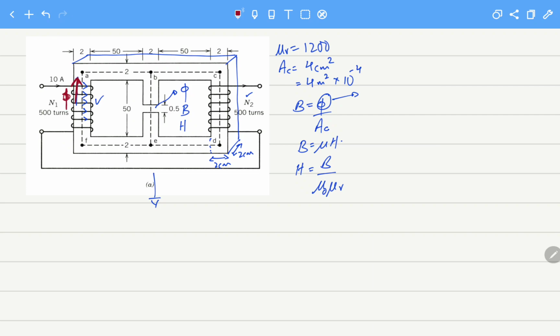Let's look at the second coil. Here also, where is the direction of the current? Here it is like this, and this. If my right hand's fingers curl in the direction of the current flowing in the coil, again my thumb will point, and the flux direction will be this one. So I call this flux 1, and I call this flux 2.